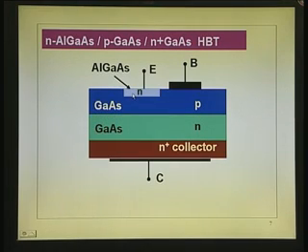So what you see here is the N-type region with doping of the order of 10 to the power 17, aluminum gallium arsenide. You do not want to go to too much X, because then you will have problems with that aluminum content, and you will also have problems making a good ohmic contact here. So you choose X of 0.1, 0.2, and you will get that high band gap difference between the emitter and the base. This is a generic HBT that has been used. The first heterostructures used were AlGaAs on GaAs, because there is good lattice match. Gallium arsenide is 1.43 and this can be 1.73, so you get 0.3, and a beta which is very high.